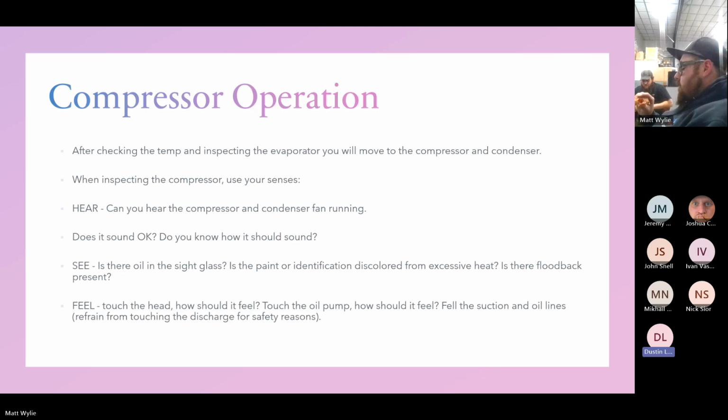It's like a switch. If your compressor contactor is pulled in, one on the top to one on the bottom is the same leg of power. It's going through the switch of the contactor. If that contact is making a good connection, you should read 0. There should be no voltage drop from one on the top to one on the bottom.